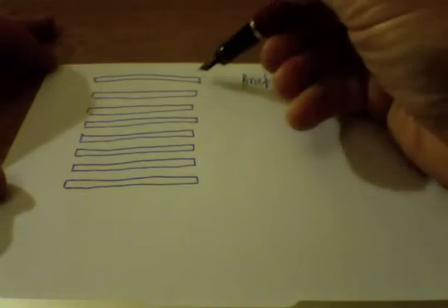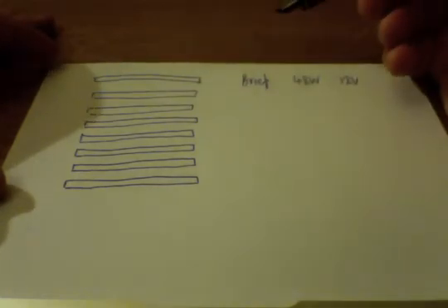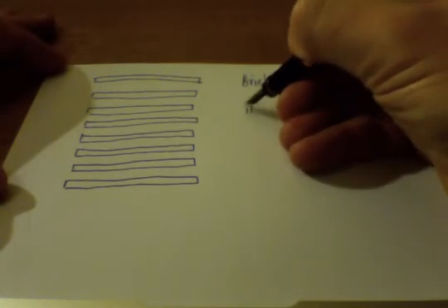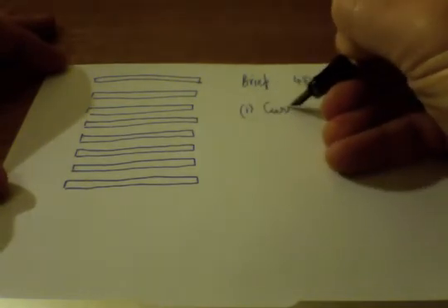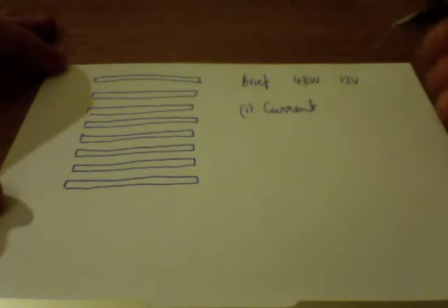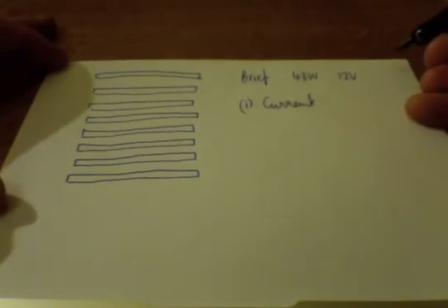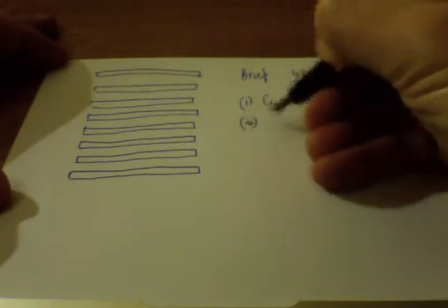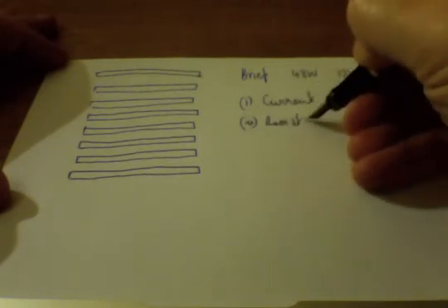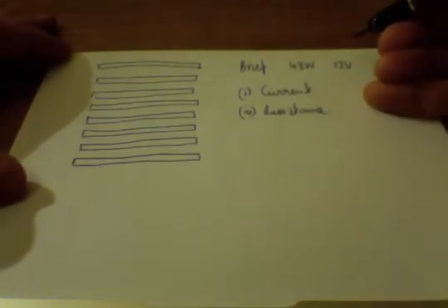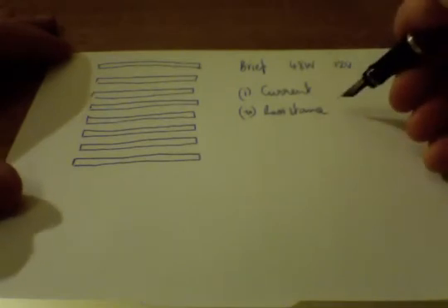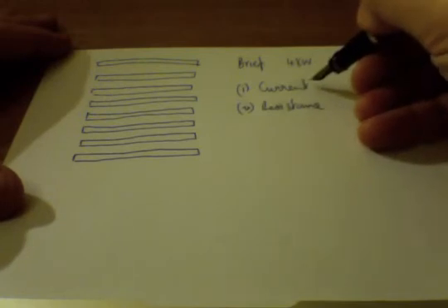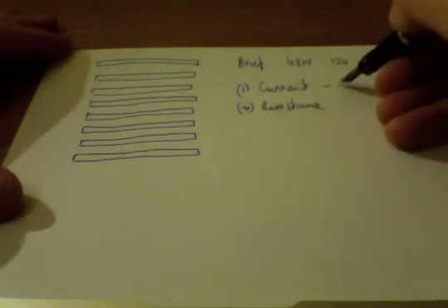And we're going to try putting it together in a parallel and series combination and work out for both, firstly, the current that's drawn in a parallel and series combination, the resistance of each, in the parallel and series combination. And I suppose it would be helpful if you work out the current, total current, and then the individual current.